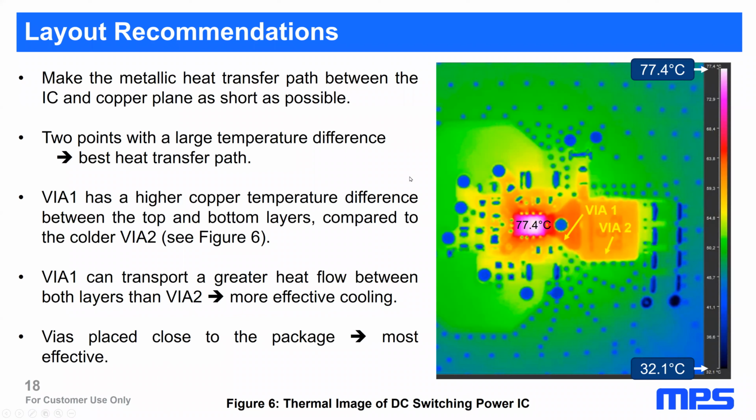That's the V-in polygon, the thermal vias, here and here, the top plane for the ground around, and the inductance. That's the only chance to cool down the IC.